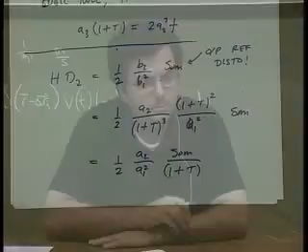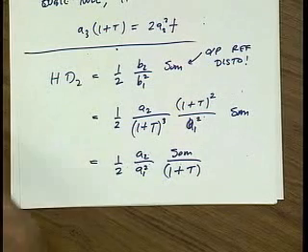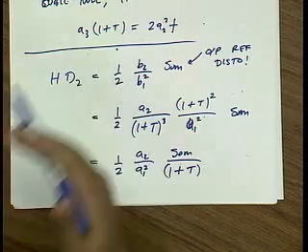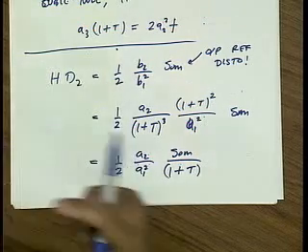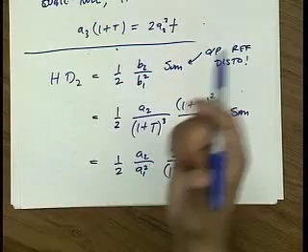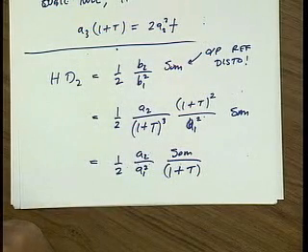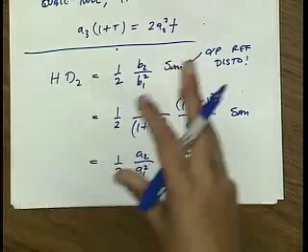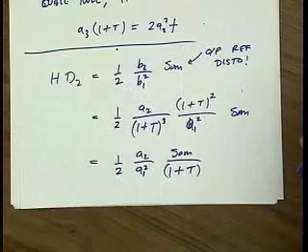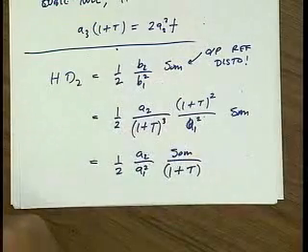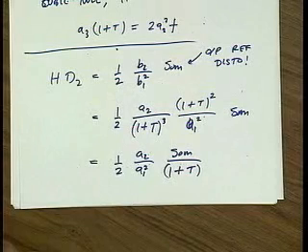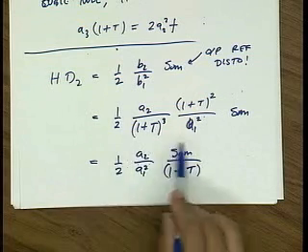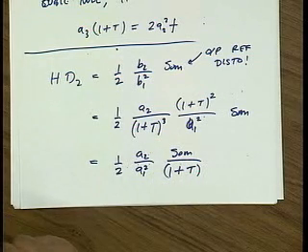Basically, we know that feedback reduces the gain of the amplifier. So because of the feedback, I'm going to get less signal at the output. So I might as well compare apples to apples. At the end of the day, I need a certain output signal. So that's why I do output referred HD3. Because if I just do input referred HD3, it's not fair. I can't compare my original amplifier to the one with the feedback, because the original amplifier had more gain. I've killed that gain by putting feedback in. But even though I did that, I still have improvement. The output referred HD3 gets better.